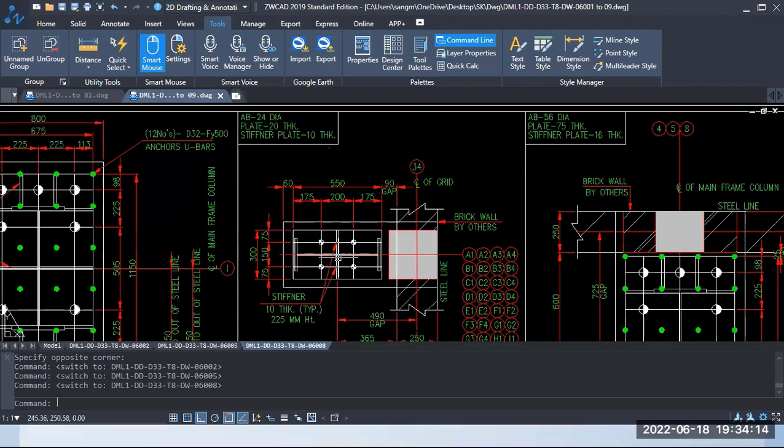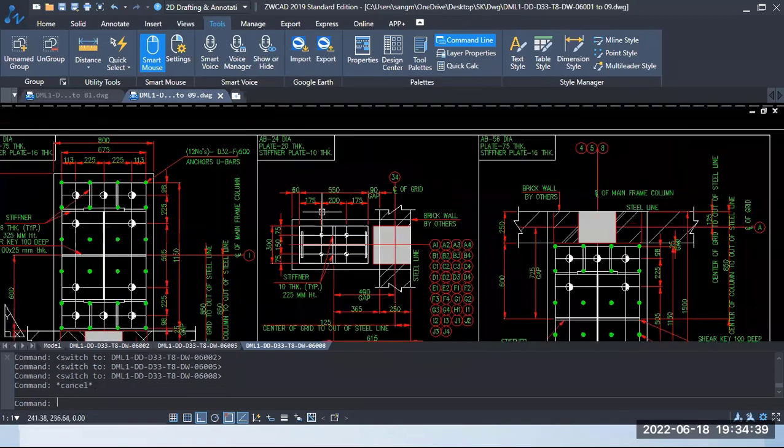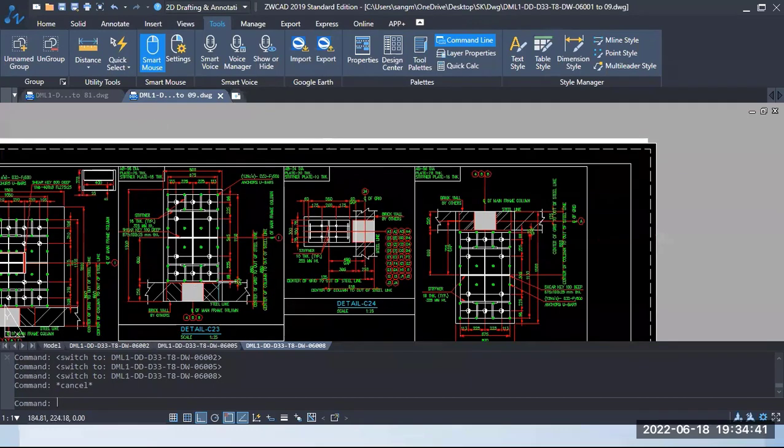Calculating the forces in the bolts, the tension force or shear force in the anchor bolt, and this will be designed for bending because of compressive force as well as the tension in the bolts. Accordingly, the base plate size and thickness will be decided, and the anchor bolt size will be based on the tension force as well as the shear force being transferred. Okay, this is all about the pin base and fixed base.